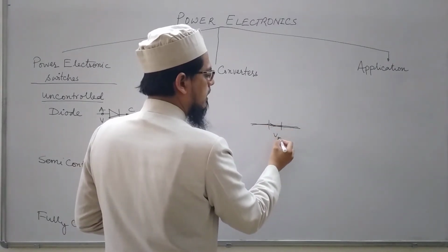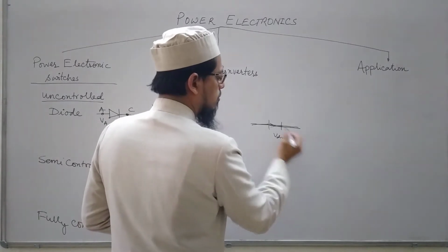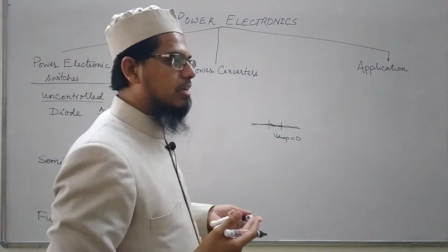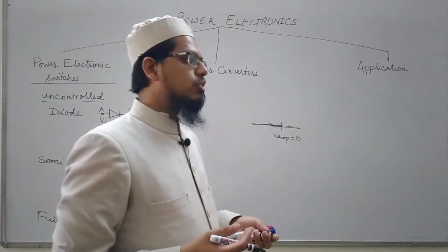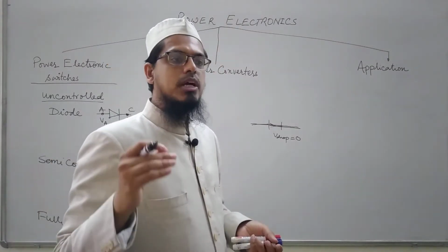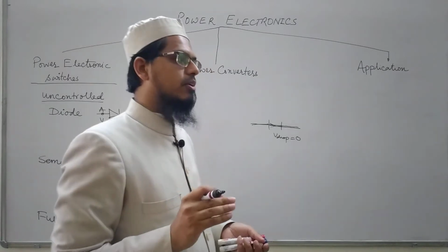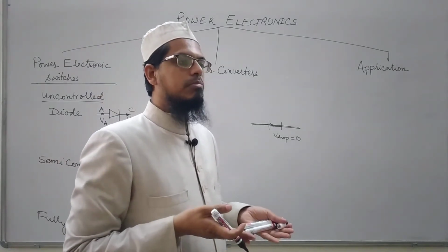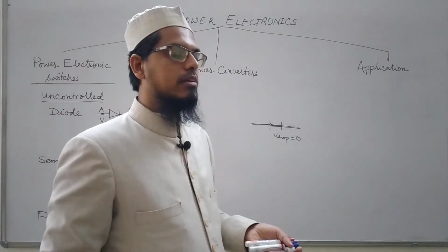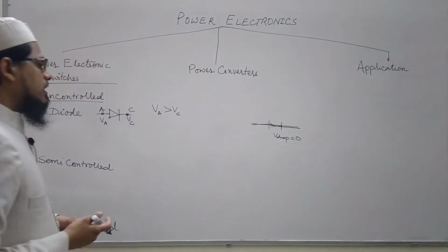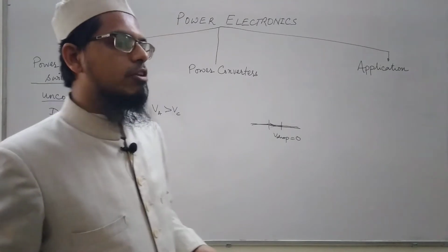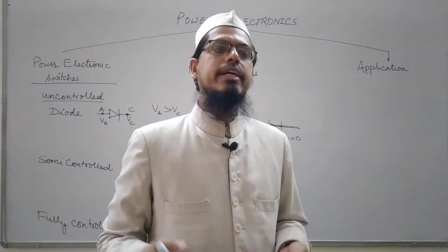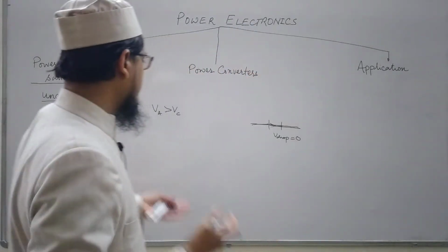The V drop should be equal to 0 ideally. But we will see that in a power electronic switch we do have some small drop appearing across the device, and a better switch is one which has got this drop as low as possible. But in the analysis that we will be doing in subsequent chapters, we will assume that this drop is ideally equal to 0.